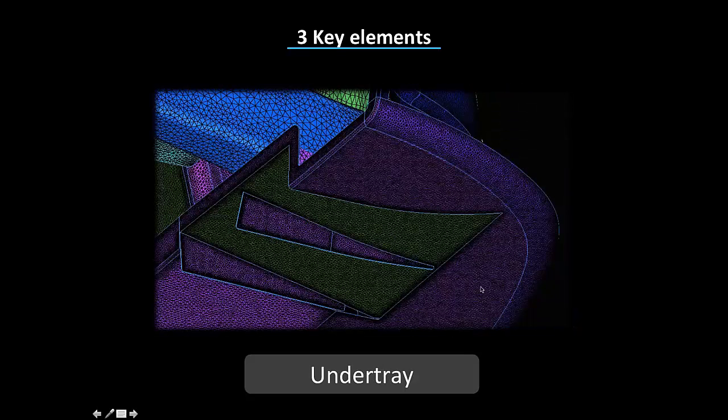So the under tray, you can see here on the under tray there's a little diffuser tunnel built into it. So diffuser tunnels are handy. Generally with your inflection point, you'll see your low pressure peaks on them. One thing that helps with flow attachment and efficiency on diffuser tunnels is the strakes. So you can see two strakes in the Supercar tunnel there.